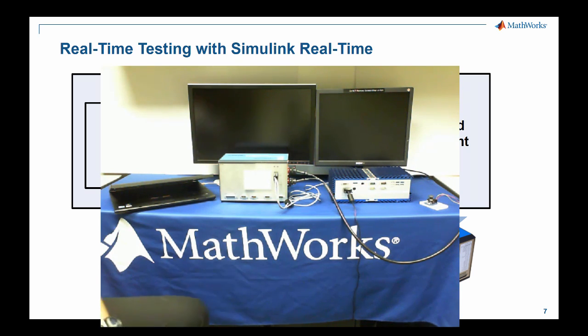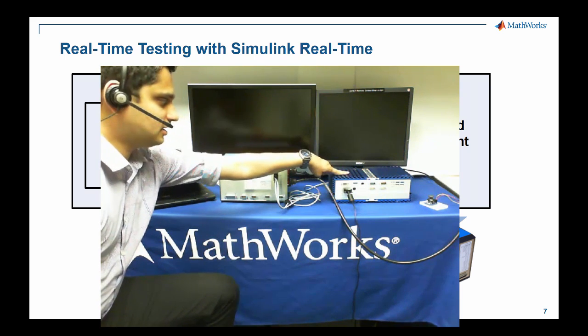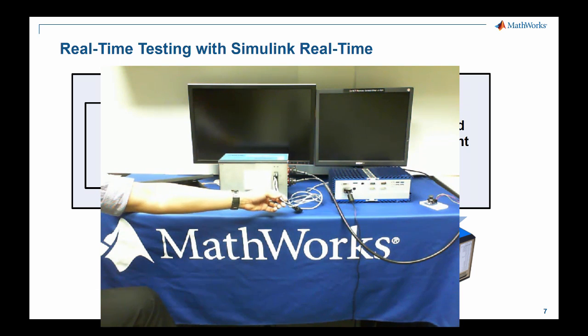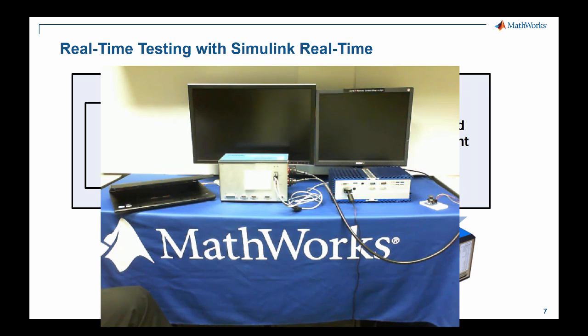So in my office, I have this one SpeedGoat target computer running the control algorithm, and I'm running the vehicle, environment, and the sensor models on this second SpeedGoat target computer. And I'm doing this because my prototype test vehicle isn't ready as yet. This is that CAN cable connecting these two real-time systems. And in order to visualize the signals and get a better understanding of what's happening during the test, we have also augmented Simulink Real-Time with Unreal Gaming Engine, which is running on a separate laptop over here, but will be displayed on this monitor.